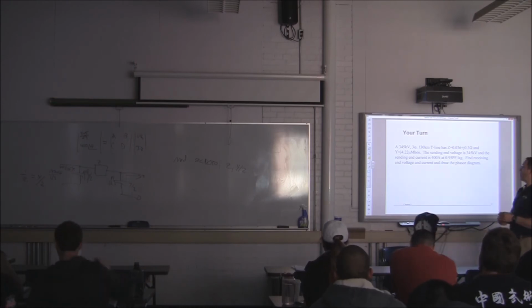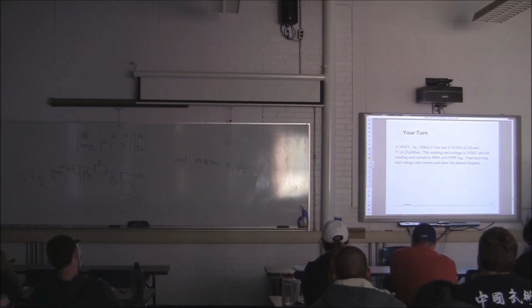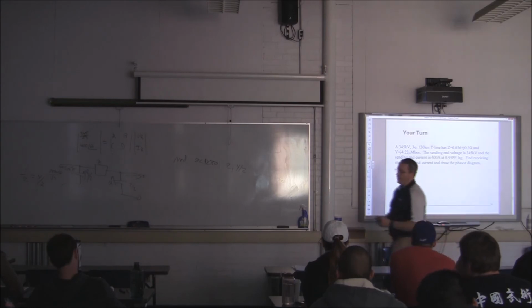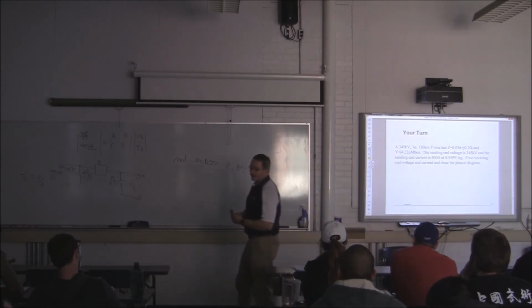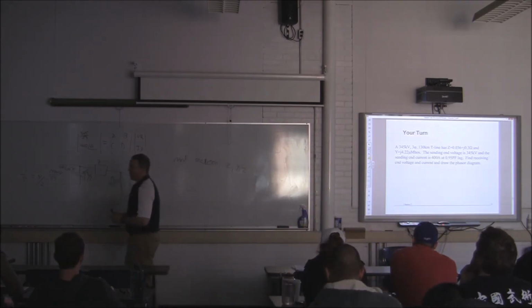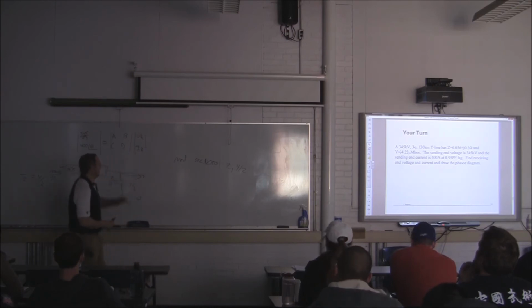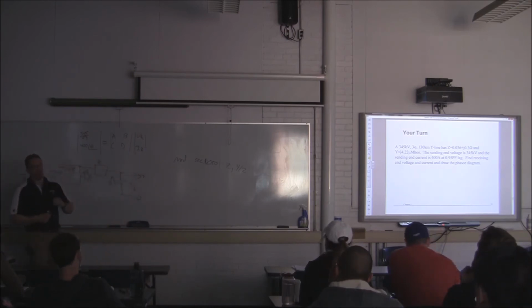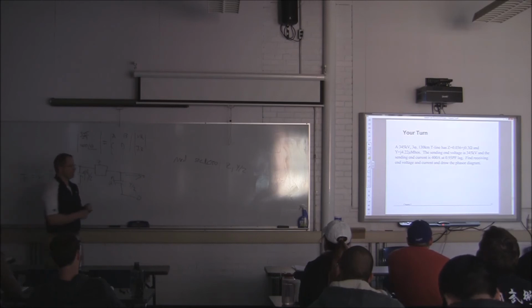Is this a short, medium, or long line? Medium line. So, you don't need to do that here. So you solve for your A, B, C, D. Then you can invert and back calculate your VR and your IR.